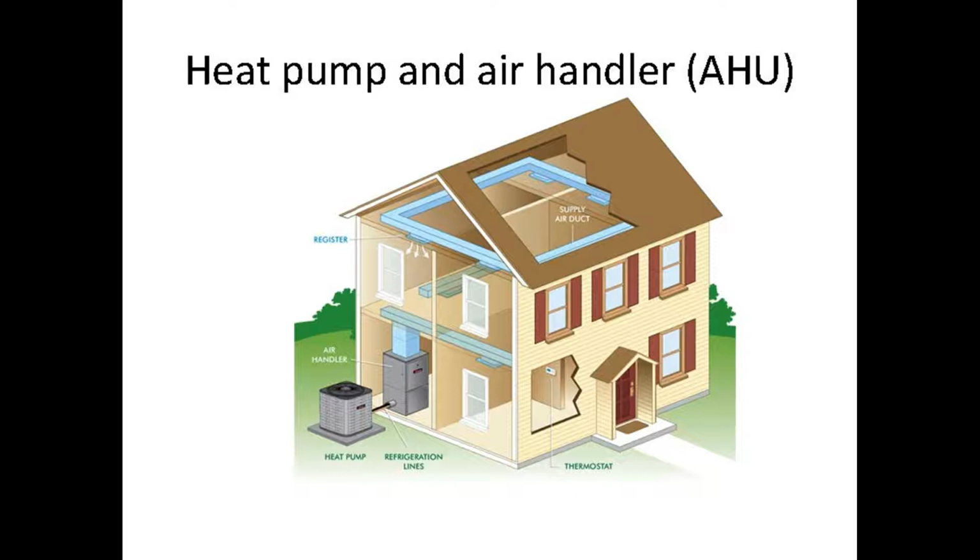So the objective is to put the right size grill and the right size ductwork and the right amount of air in each room to get the house to be comfortable and basically the same temperature in every room.